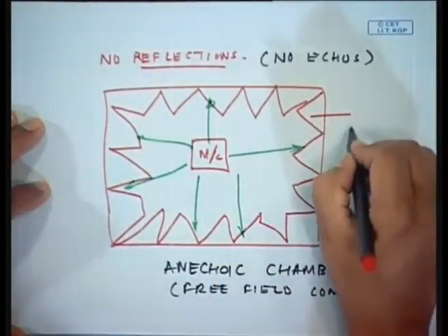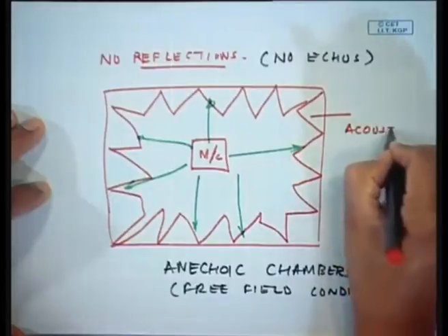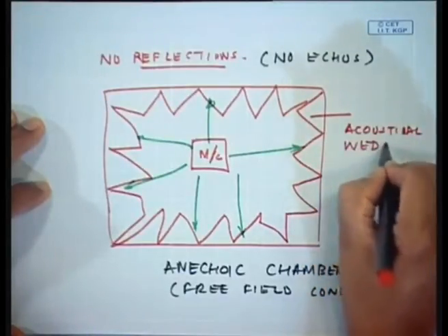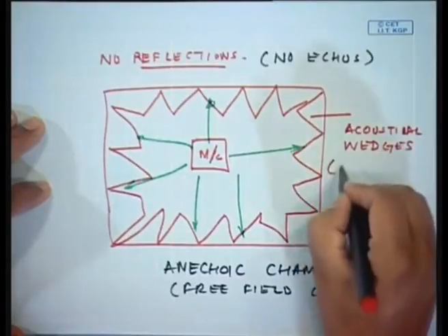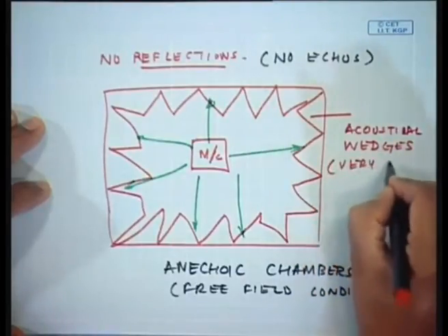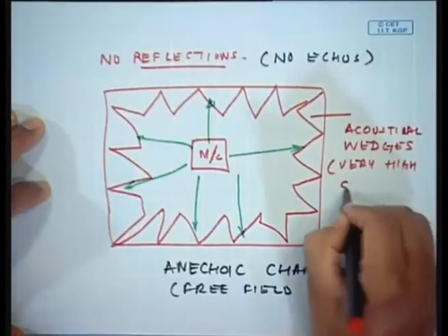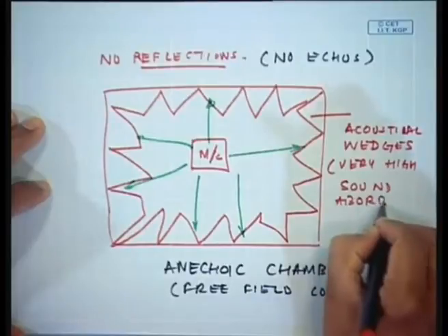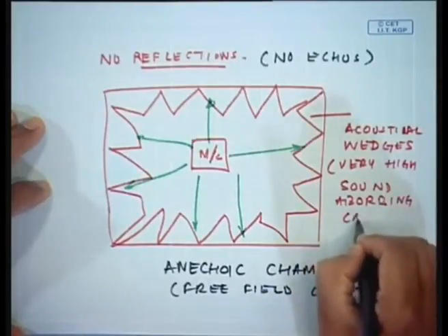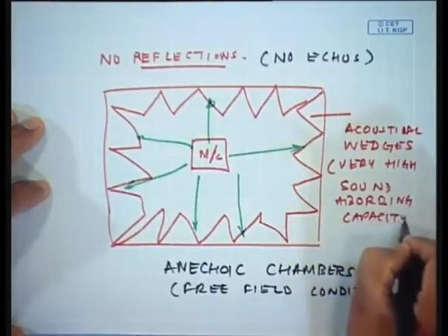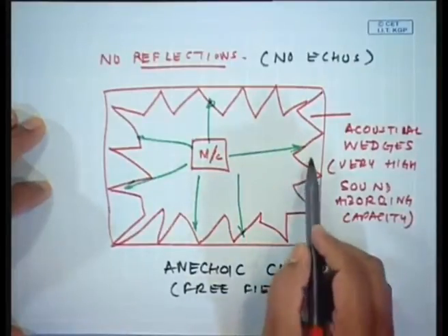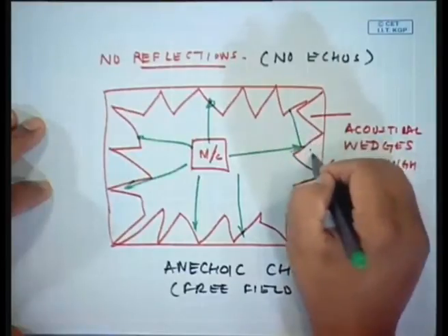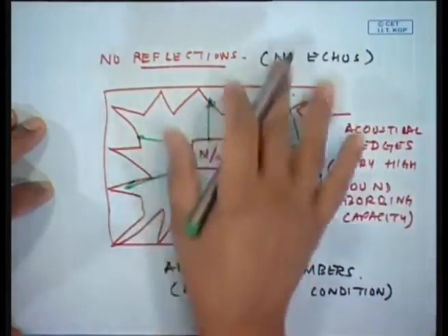And these are actually acoustical wedges having a very high sound absorbing capacity is what I will say right now. So, any wave which goes in here gets reflected and gets trapped in this material, and so this is a free field condition.